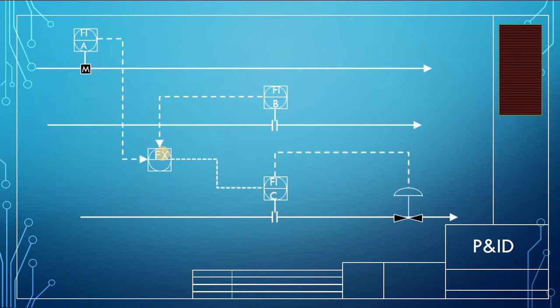And another example here: if we have A, B and C fluids, you are mixing them based on functions, or based on equations, or based on a table. So you measure A and B, and then you go into the table and figure out what is the required flow rate of the third component C, and this becomes your remote set point for your FIC here.